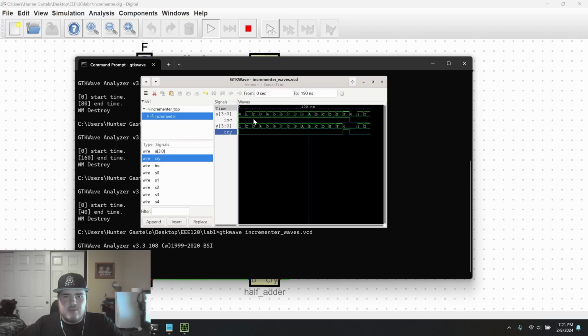And we see through A being 0 through F and incrementer being 1, it adds 1 every time. And in that case of A being F, it reverts to 0, causing overflow. And when incrementer is 0, it's just going to be equal to A.